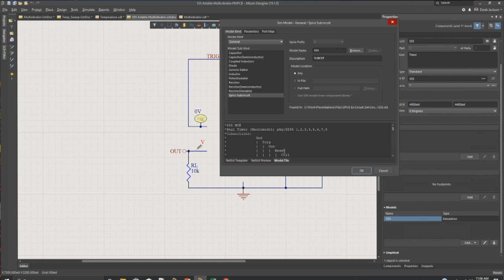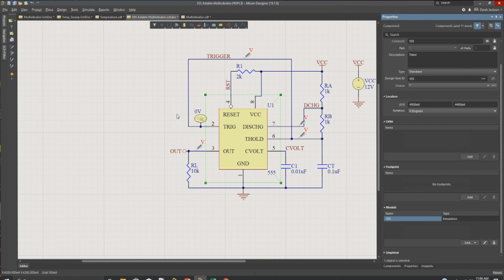And we go and look at the model file, and that might be kind of small, but see they have initial mapping, so they'll show how they are mapping with these. They have little dashes down here on how they're mapping that. And they have a collection of components, resistors, controlled sources, and everything to run that. And a lot of times when you download a model from a manufacturer, they might have some notes in there saying, this model was derived using this particular advanced parameter. Gmin is set at this value, or that. So you want to make sure you read through the comments in the model, because sometimes there's some specific tweaking you need to do to get it to work.